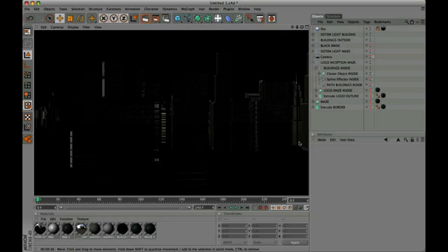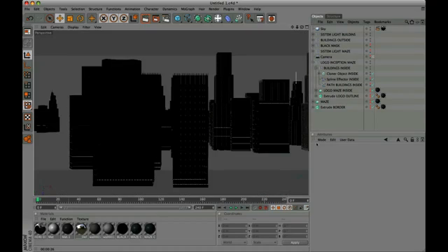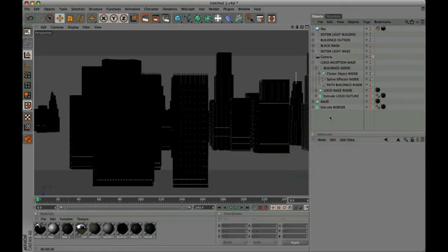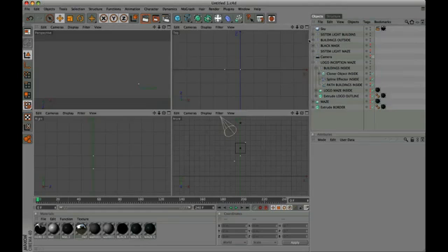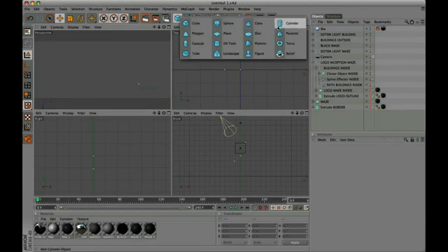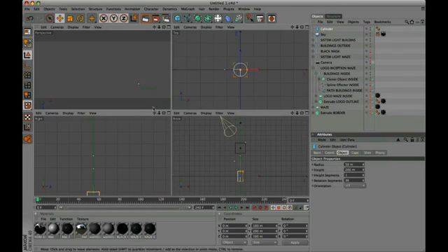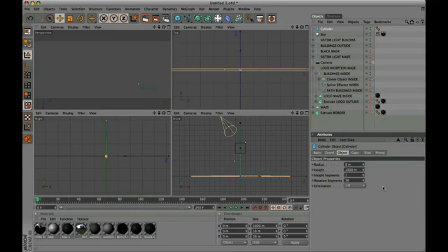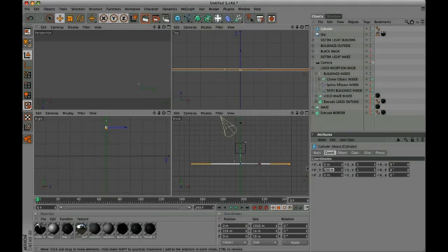Now, in our stage, add 2 cylinders with neon effect, to reflect light on skyscrapers' windows. Add the first cylinder, oriented along x-axis. And change the size: radius 8, and height 19-20 meters. The position coordinates are y, 300, and z, minus 3 meters.